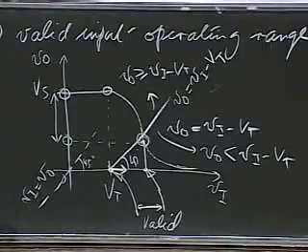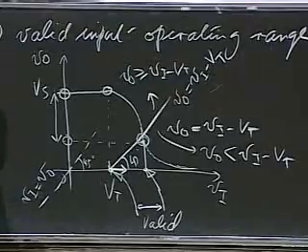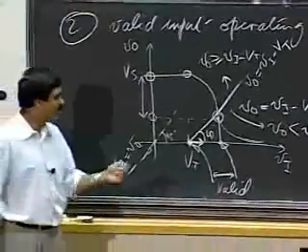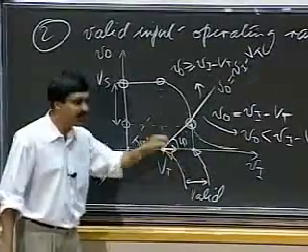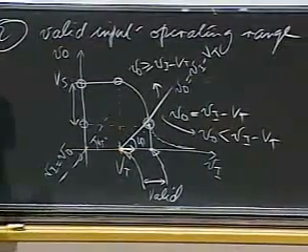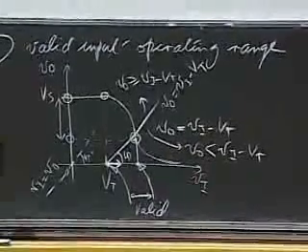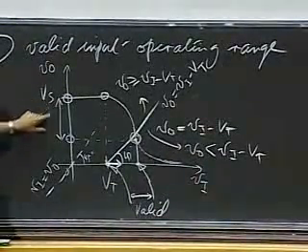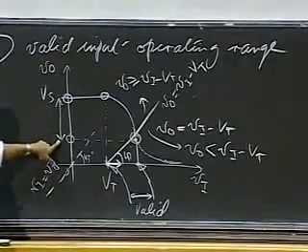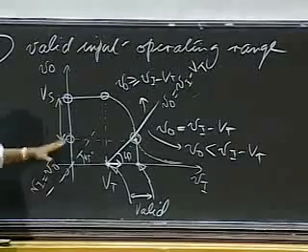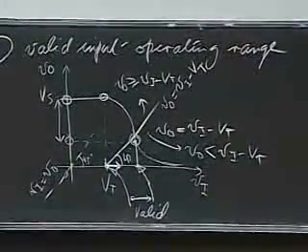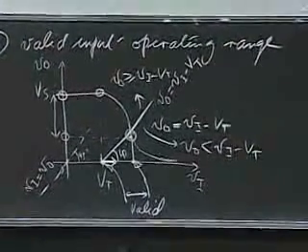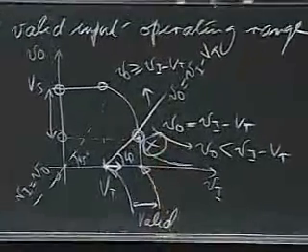So what does this say? What this is saying is that if I, as the designer of the circuit, am disciplined enough to apply inputs that are in this range, Vt, to some value here, graphically shown here, then my MOSFET will remain in saturation. And correspondingly, my outputs will go between Vs and some value here. Okay? So hopefully that gives you some of the intuition behind how we get it. And let's continue. Let me label this point X.